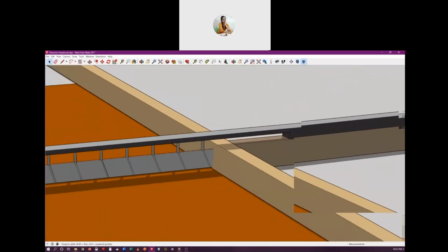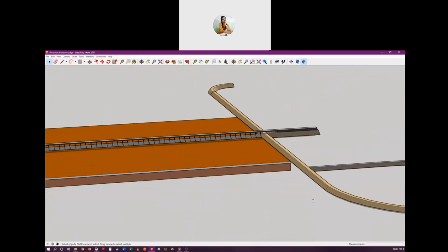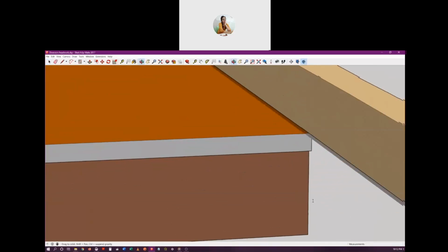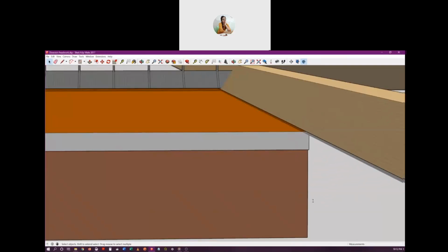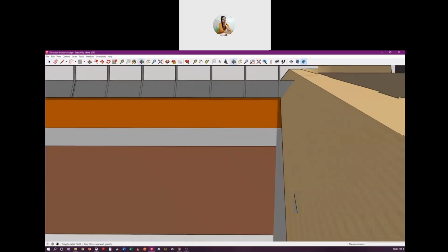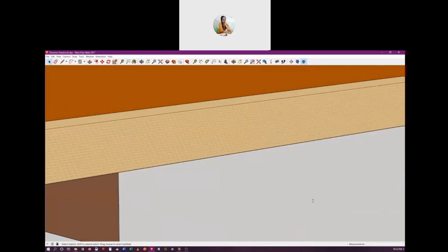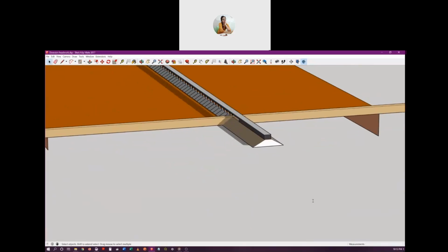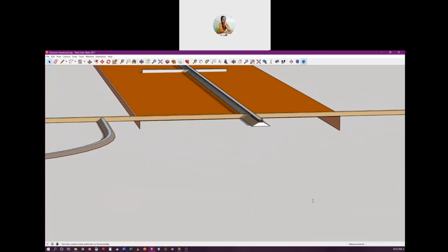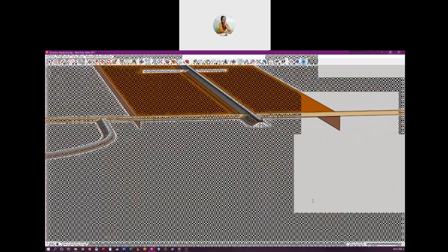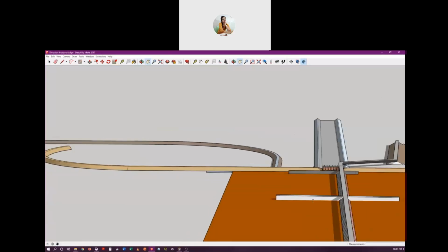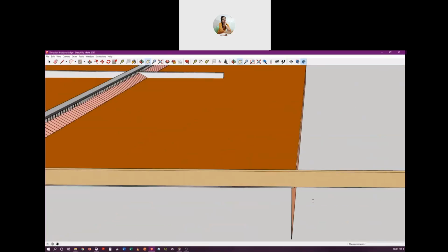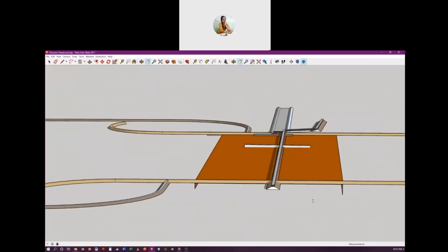And one more thing that I forgot to mention is that you see these cut-off walls or the sheet piles. These are provided here so that water doesn't simply flow straight from this point to the downstream end of the impervious floor. Because of the provision of these cutoffs, the water will have to take a longer path. It has to first go down, then up, then again horizontally, then again in this cutoff it has to go down, then up. So it increases the length of flow.